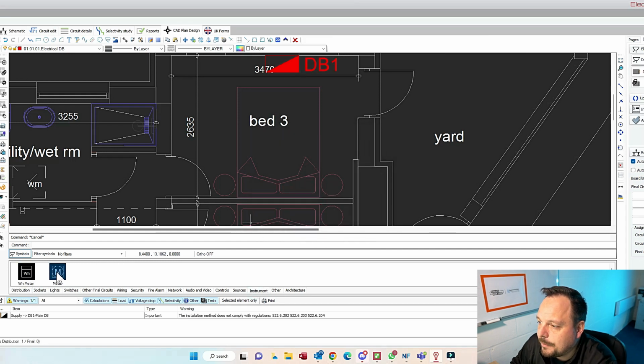You see I've dropped a distribution board straight in. This is a single phase domestic setting, a 14-way board. We're going to use a Proteus one, and I'm just dropping the meter onto the same wall in close proximity to that. Now you can use a snap to fit drawing for the wire, but I'm going to do this one manually. You just need to link the 2 points together, because if you don't, then the software won't see that those things are connected. So I'm just going to drop a wire in.